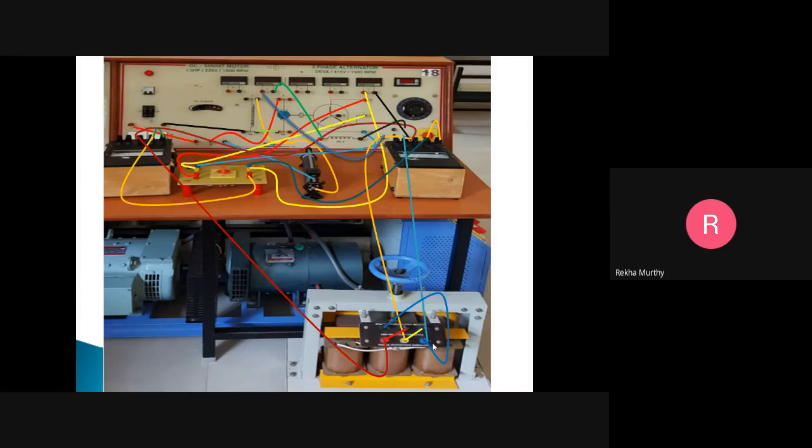The only thing is we require the ZPF point. We require one point on the ZPF curve. So let me follow that procedure. The circuit will be rigged up as shown, and with the SPST and TPST switches both in the open state, and the rheostat will be in the cutout position.